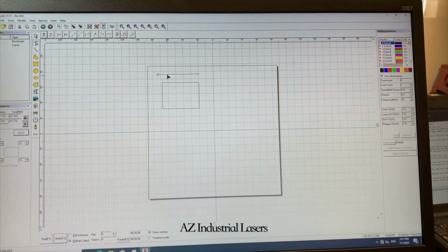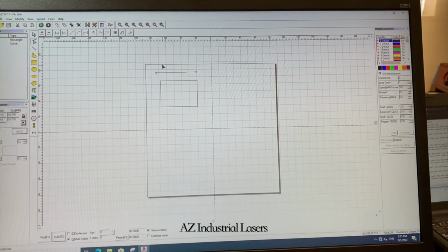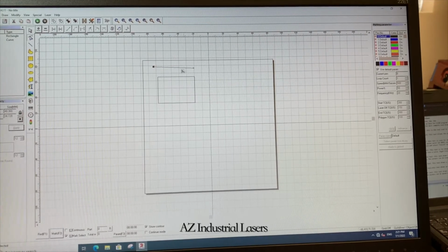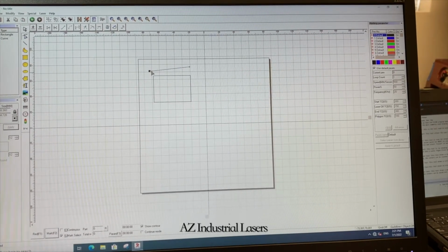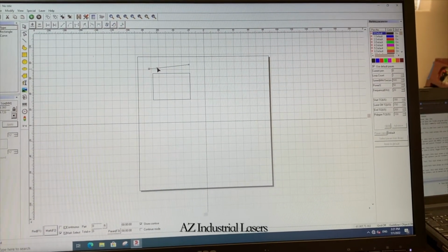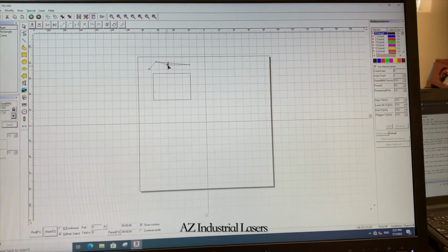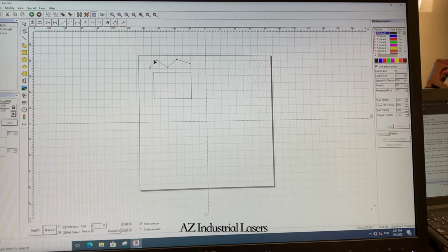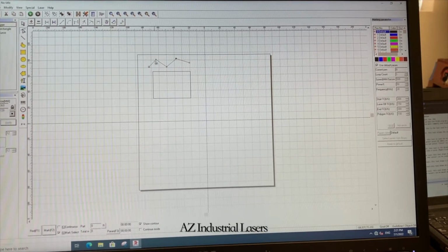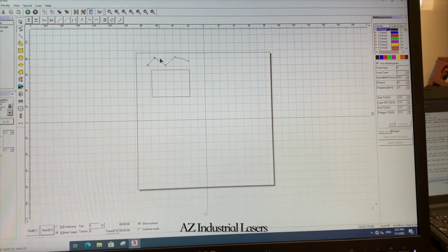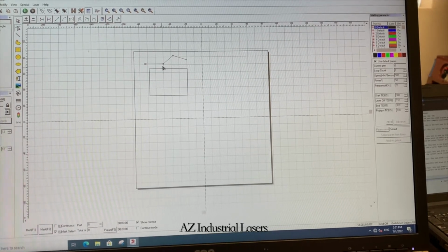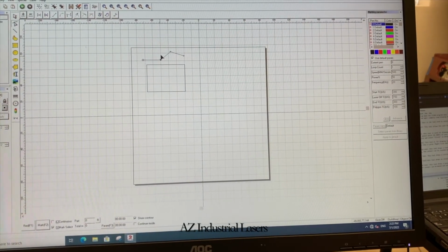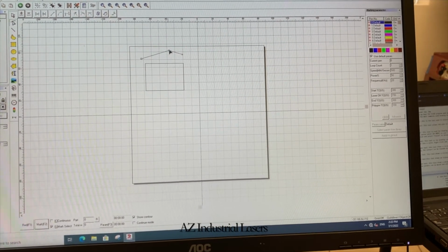But on a line or a polygon or something similar to that you draw yourself, you see here the endpoints, obviously, but you can also double click anywhere on the line to place another point, which then allows you to move where that line actually goes. So that's what the nodes are. They're just there to show where direction changes. And you can also click and select them and then delete them, which will take away that single node and then draw a straight line from the two closest points that are connected on the same path.